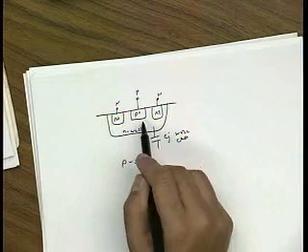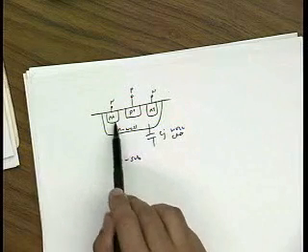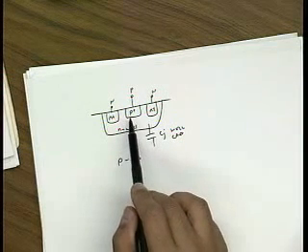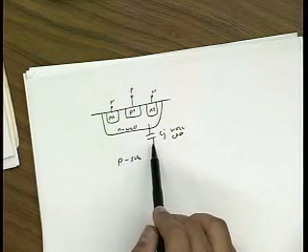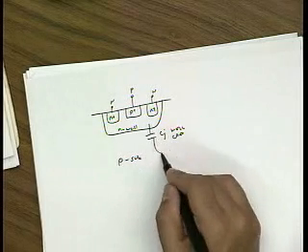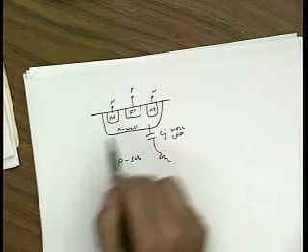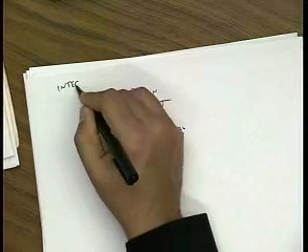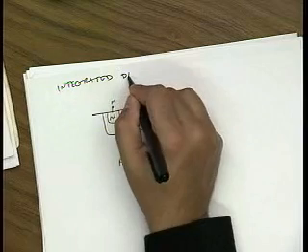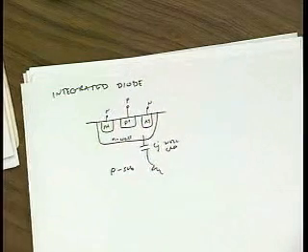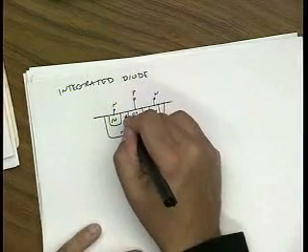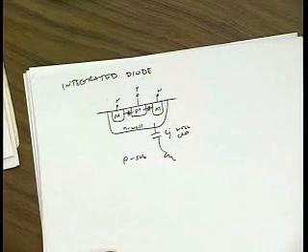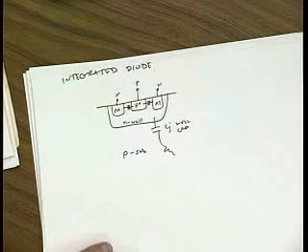Because when the diode is turned on, right, there's two paths. There's a path through this small resistance, and then there's this path through this junction capacitance and then substrate resistance. And most of the current will take this PN junction path. So this is an integrated diode. Okay, any other questions?